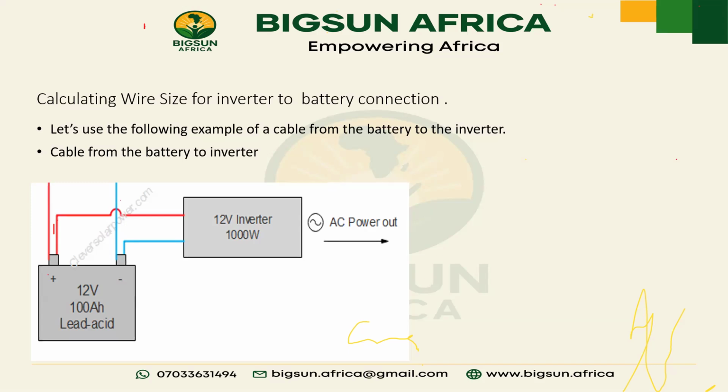If you want to use 4 batteries for a 12 volt inverter, we will connect the 4 batteries in parallel. That is, all the positives will be connected together and all the negatives will also be connected together. Then connect it to the inverter.